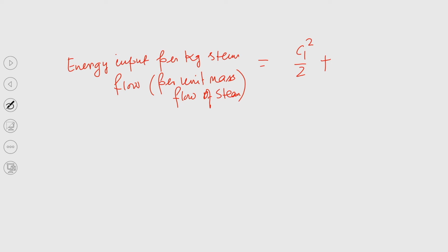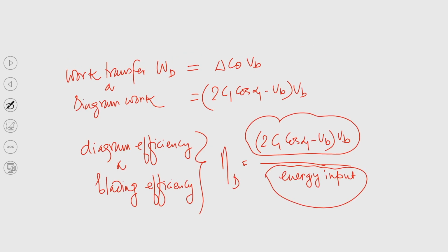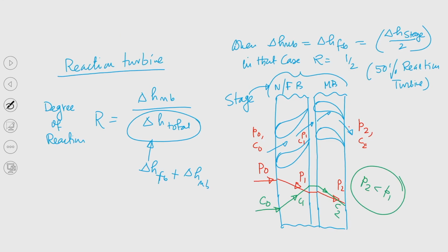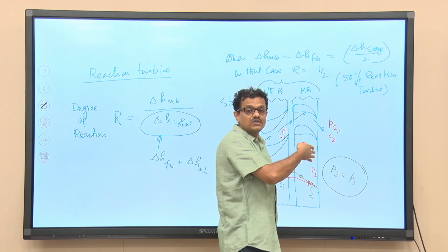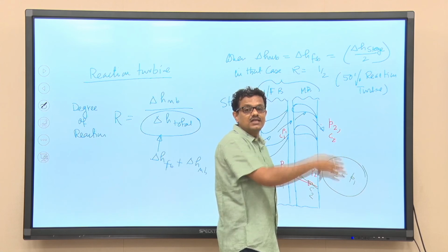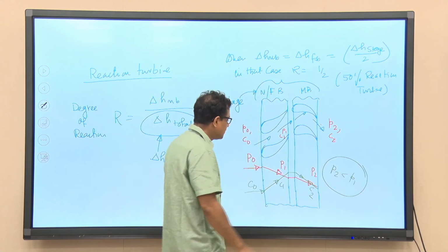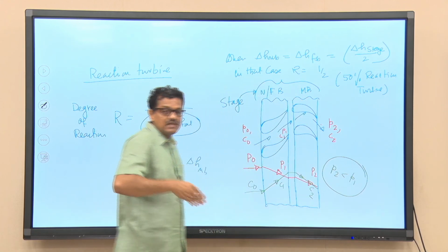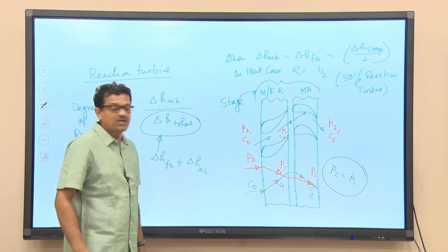but in case of a reaction turbine, if we go back to the previous slide wherein I have drawn the blades, impulse action is there, and on top of that we also have the reaction force. That reaction force is developed only because of the reduction in the relative velocity. So, basically when the steam is passing through the row of moving blades, there is a change in kinetic energy at the cost of the pressure drop.